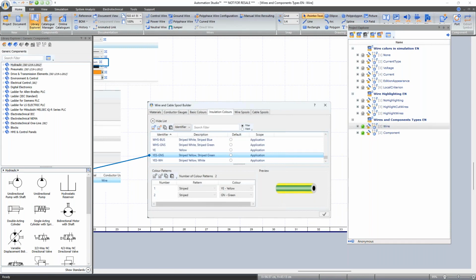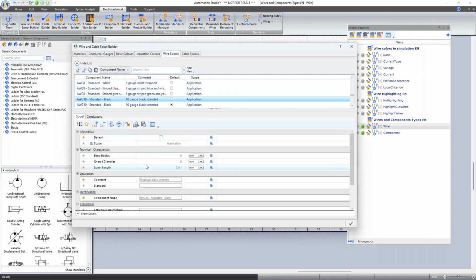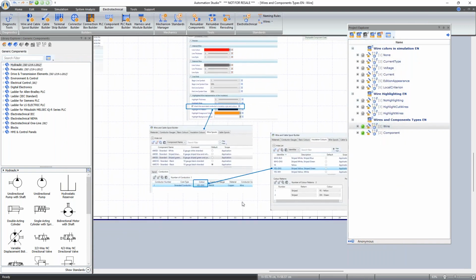Do you take into consideration resistivity in wires and cables? Yes, we do. You can see here with the wire, cable and spool builder, when you define your cables, you have the cross-section areas and other properties of the different wires. Based on that, the resistivity is taken into account. For certain wires, like we saw in the demo, if you want to neglect it, you can set them as perfect wires, and for those we don't. But basically, using the spool builders, you can create the wires and the resistance is taken into account.